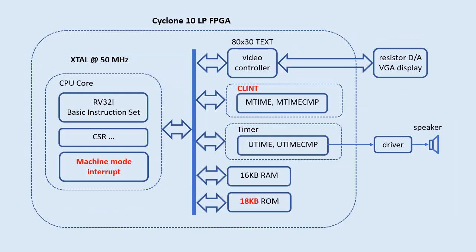In order to run FreeRTOS, I did some updates to the RV32I implementation during the process. I wrote all the programs on the previous video demo, so I can pretty much do what I wanted on the hardware and software, as I had full control of both sides. To run FreeRTOS, I'm treating the FreeRTOS software as golden, and I would update the FPGA implementation to match what the software requires. I hope this also serves as my hardware debug process.